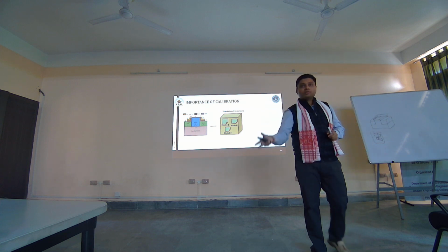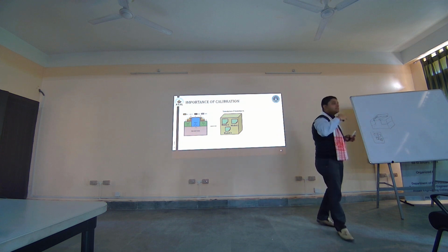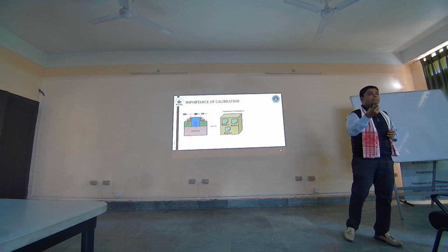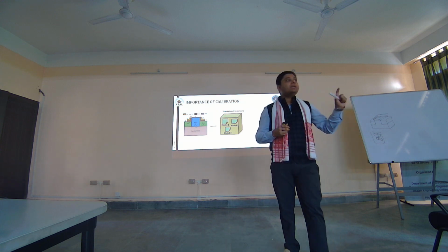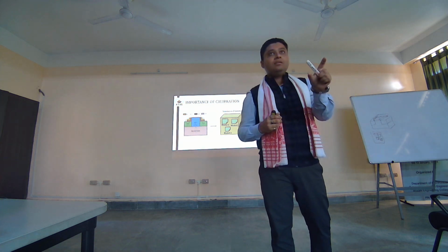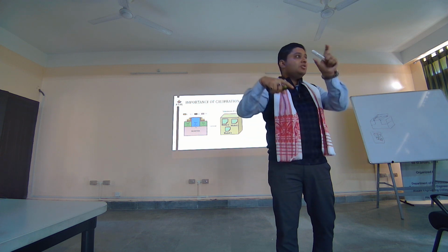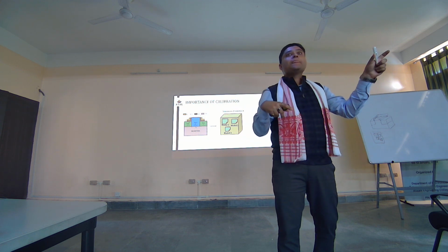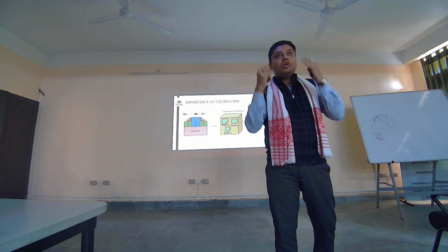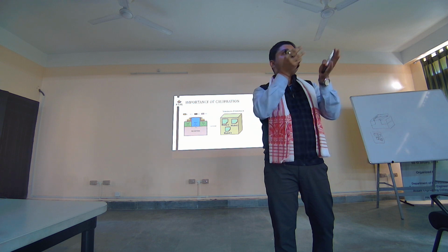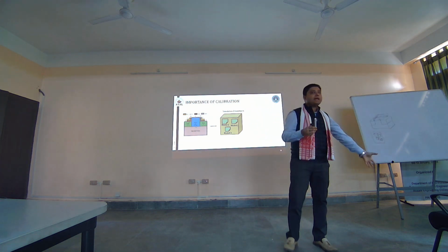There are many fitting constants, many parameters which are available for change from your end. For example, if it is I equal to mv plus c, then you cannot alter v because that is a voltage you are going to apply. You cannot change I because that is the dependent variable, right? But m and c are in your hands, and you can see whether by altering them you can mimic your current voltage characteristics with the actual device.